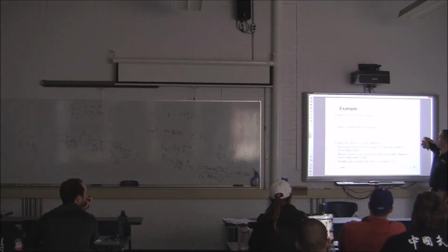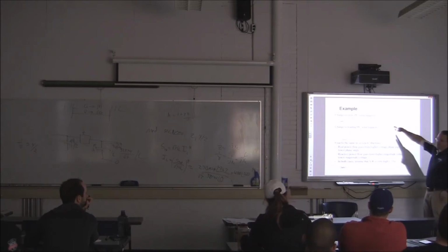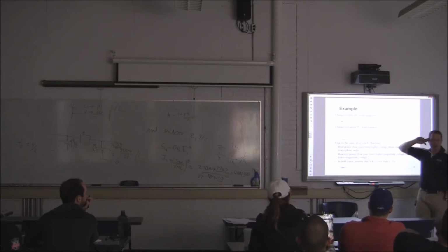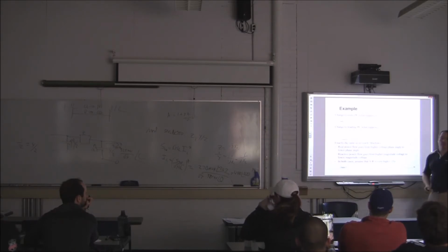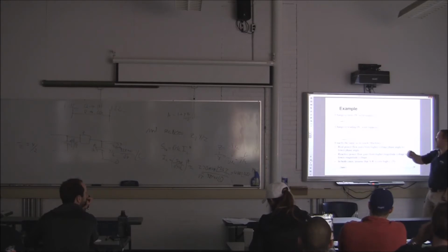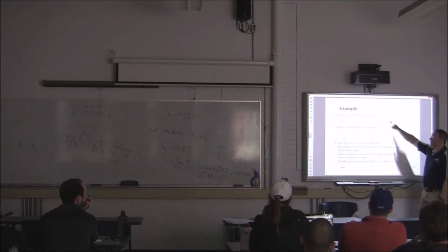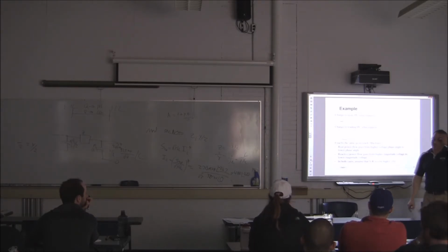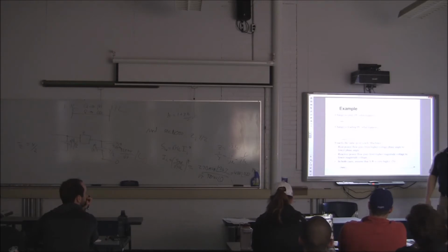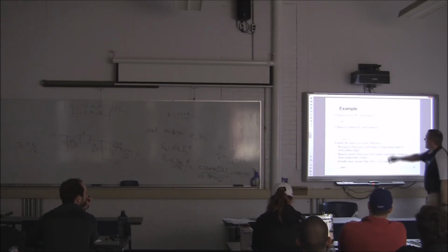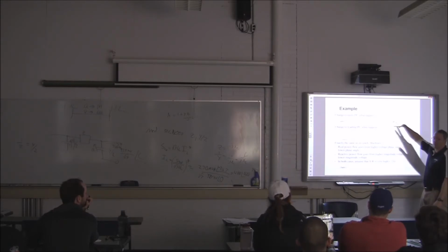Okay? So essentially now what happens is, because it's unity power factor, the reactive power going to the load is non-existent. All we have to do is support whatever line charging is required, any reactive power consumed by the line. So the magnitude of Vs, if at all, is going to be slightly greater than or slightly less than the magnitude of Vr, because none of the reactive power is really coming from the sending end. But look at the angle between Vs and Vr. It's still positive. So that means power is still flowing from Vs to Vr.